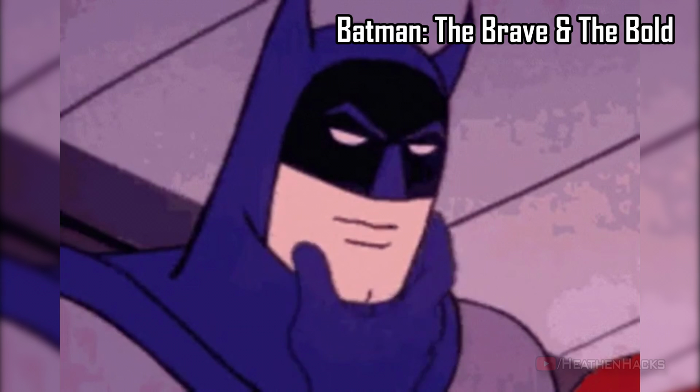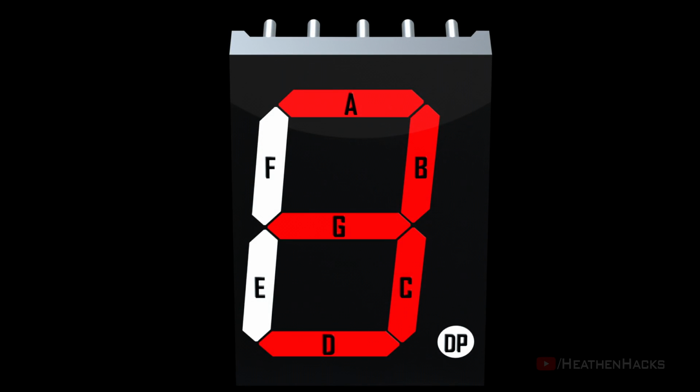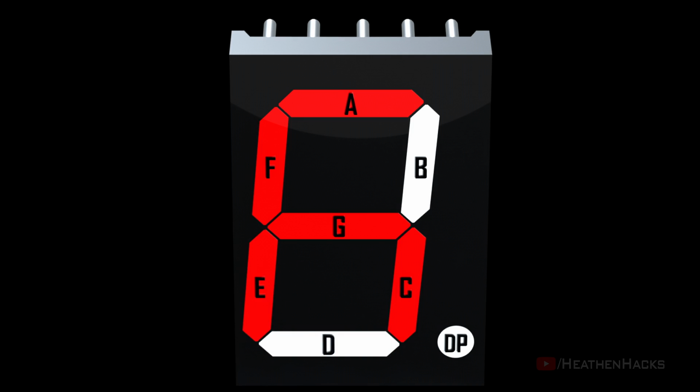As you can see, looks like we've messed some things up. By the looks of it, it seems like numbers 3, 5, and 9 were in this array. So on number 3, instead of segment D being lit up, it lit up segment E. On number 5, same as what happened to number 3, instead of segment D being lit up, it lit up segment E. And on number 9, segment D was not lit up. We clearly have some fixing to do.